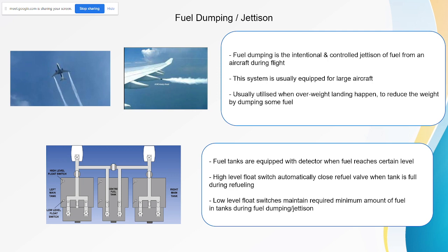Okay. So after you take off, you have the maximum weight. That means plus the fuel. The fuel might be 5,000 to 6,000 kg. So in case anything happens and you want to turn back, you have to burn this fuel. You have to let go of this weight. If not, it will be very heavy for the landing. The structure will not take it. In aircraft design, there is a limit for the landing weight. Normally, the landing weight is limited due to the fuel.